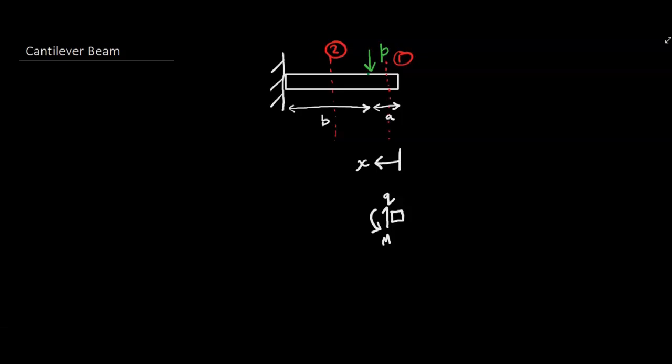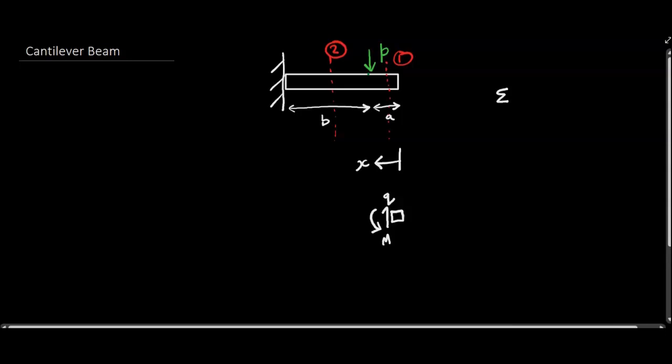And then I'm going to look at applying equilibrium. Now, if we just take a step back here away from the problem and think in general, recalling Newton's laws, we said that the sum of the forces in any particular direction, for instance x, is equal to the mass times the acceleration in that particular direction, x in this case. And there is no acceleration in our problem. It's not a dynamics problem, it's a statics problem, so this acceleration term is 0, and so therefore the sum of the forces in any particular direction must be 0.